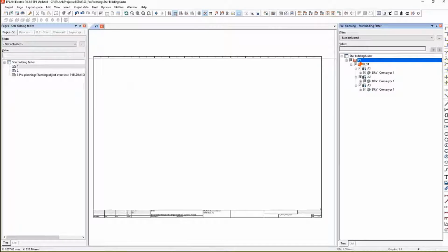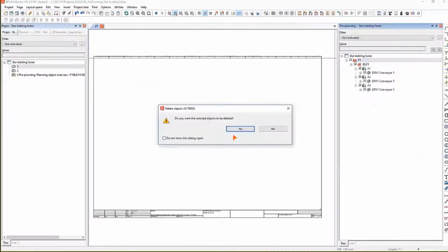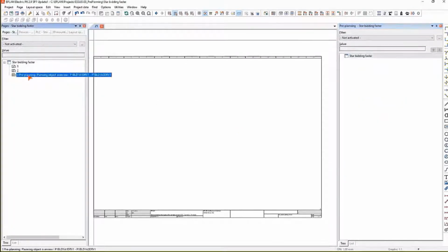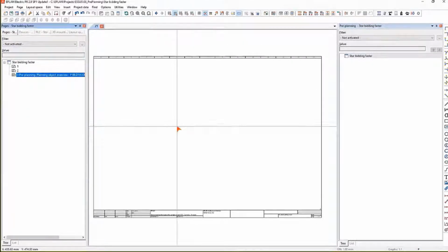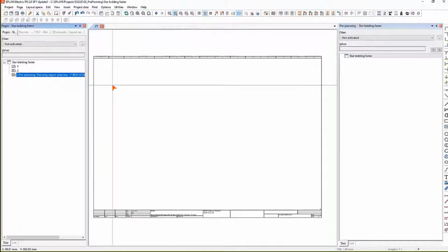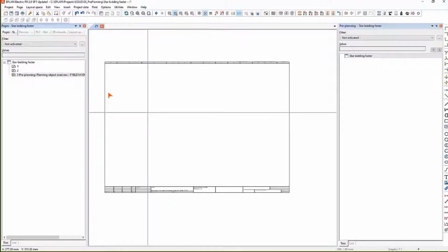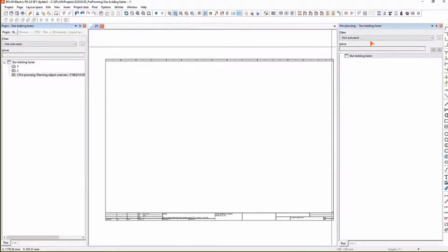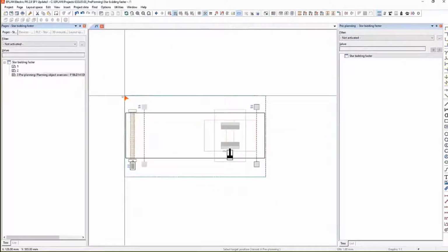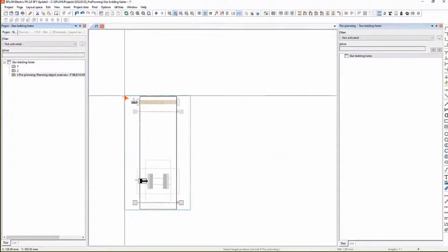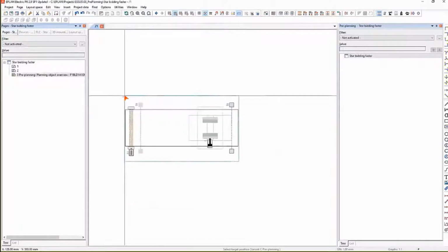So again, I'm going to delete all of this. And I'm going to remove this particular page. And now let's say I need to design a conveyor system for a manufacturing facility. I'm going to start with a conveyor, so I can use a conveyor macro. So now we're using graphical objects. This macro contains the conveyor, contains a motor, contains 2 light barriers, and a cylinder. By using my tab key, I've got 4 different variations, vertical and horizontal at different positions.